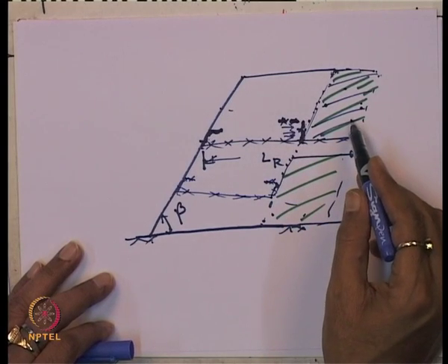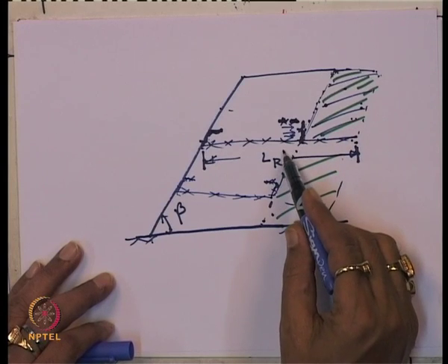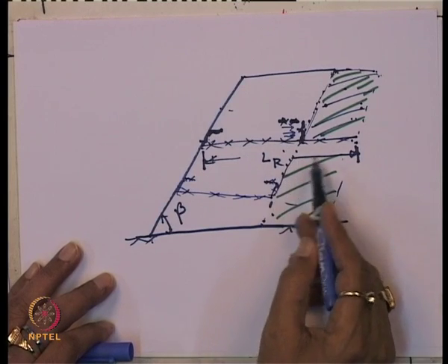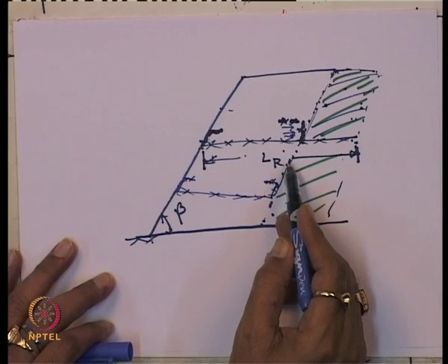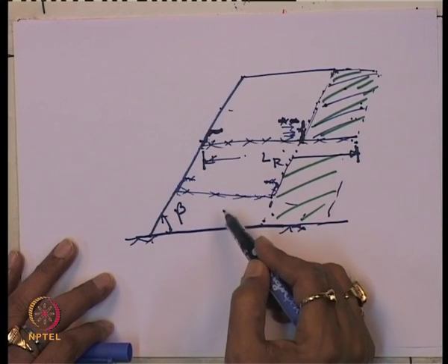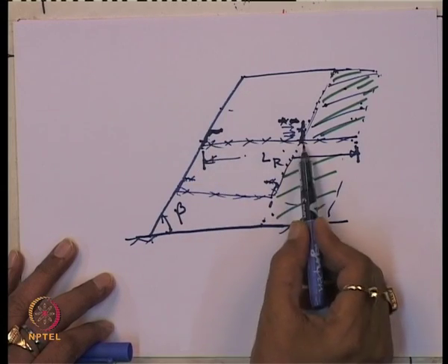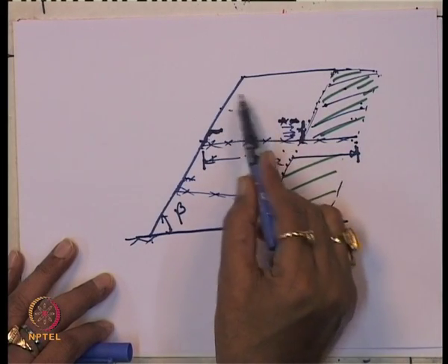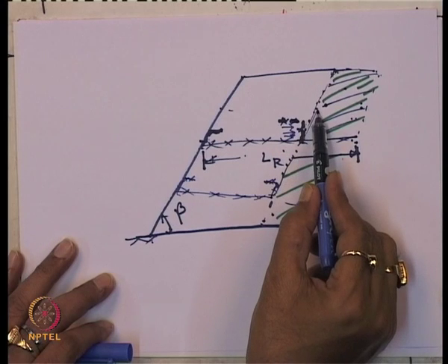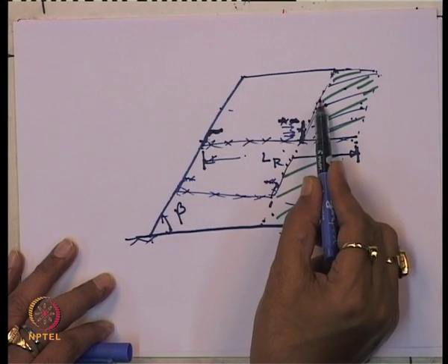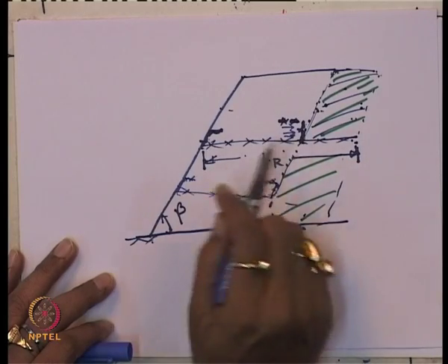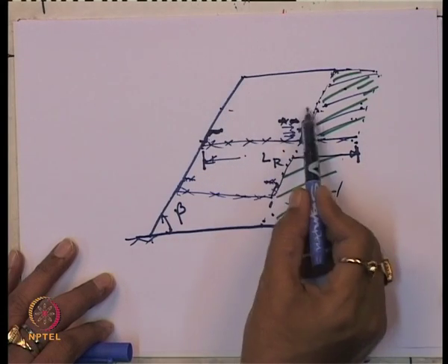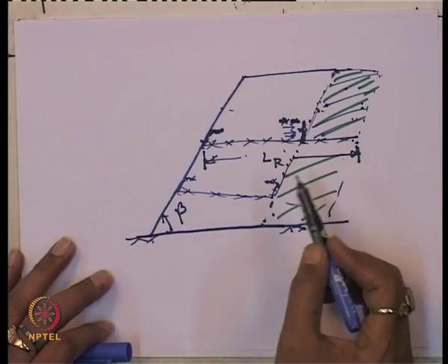So, you can save the cost, you can save the geogrid, and it will give very good passive resistance. So, you can reduce the length of the geogrid. So, this is what we call the back wrapping technique. Apart from that, instead of the geogrid, you can also place the geocell as a layer of reinforcement material. The geocell material gives a very good confinement effect. So, that way also the length of the geogrid can be reduced.